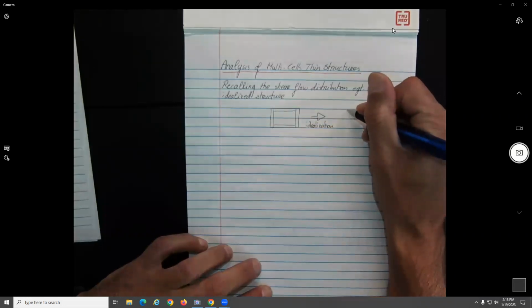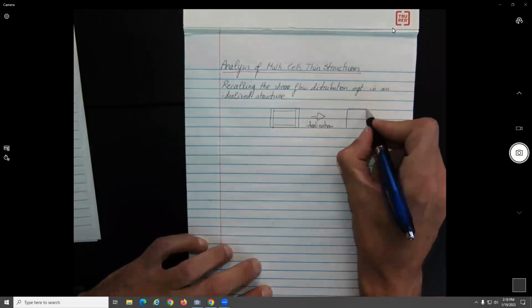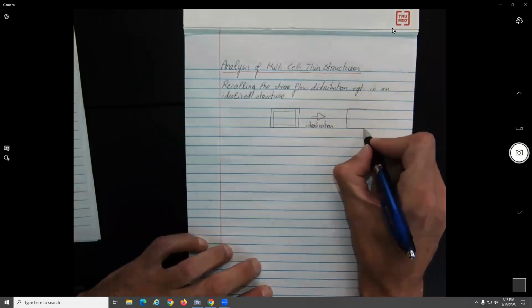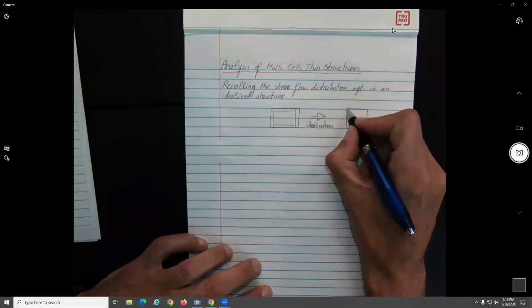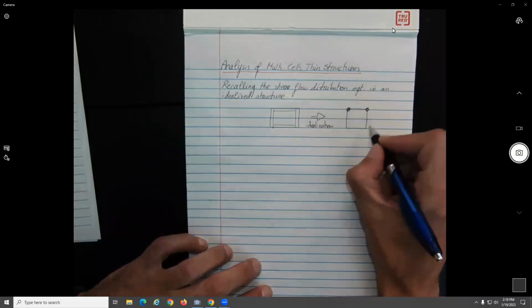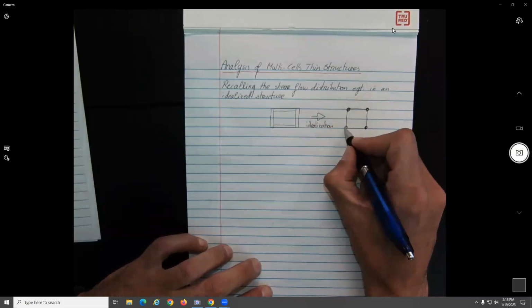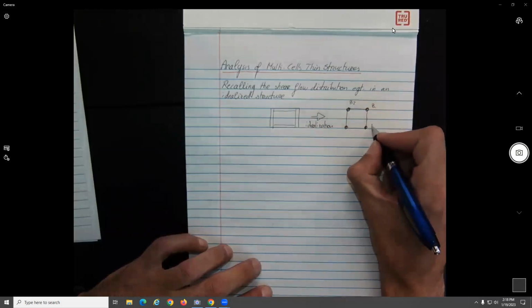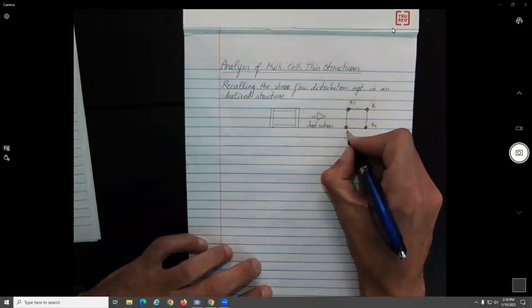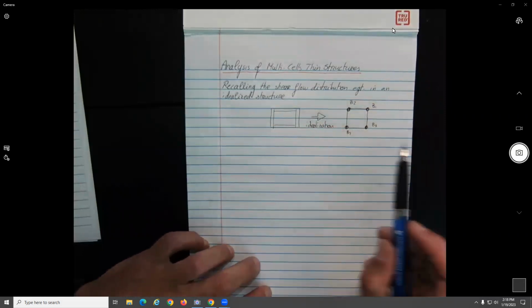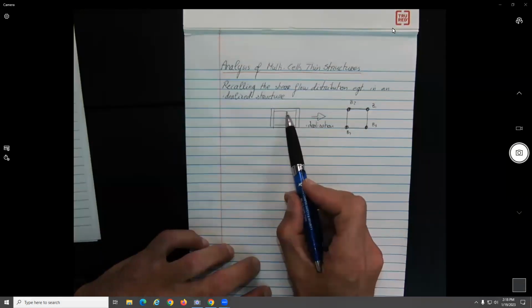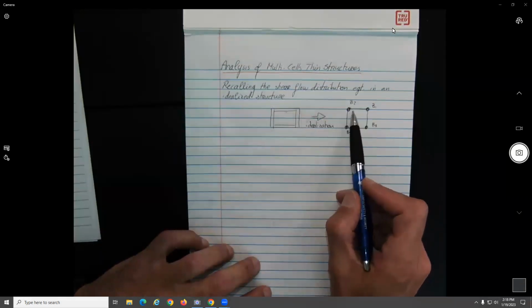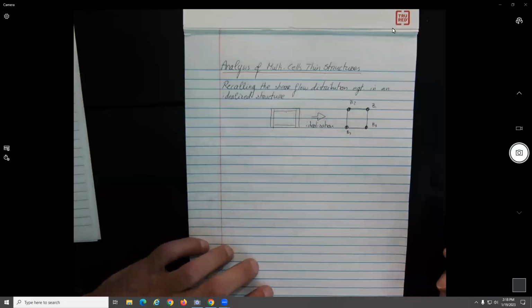I'm sure that's what you have done in Structures 1 for open sections. Okay, I'm doing here a closed section, but you move all the area before, where basically you take all the area of this stiffener and model it by this one over here, by equivalent areas.